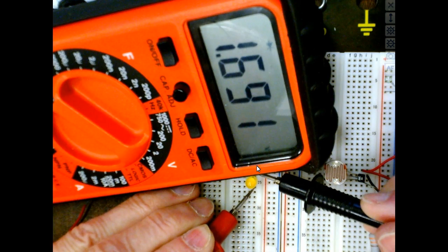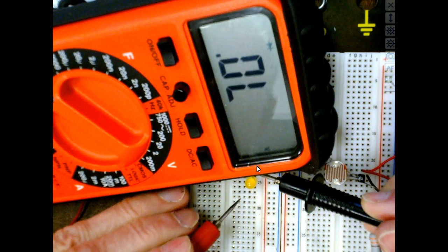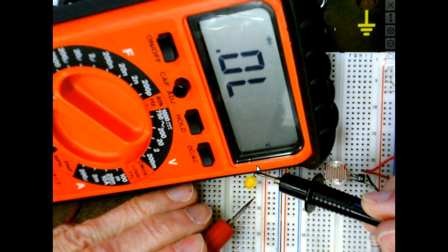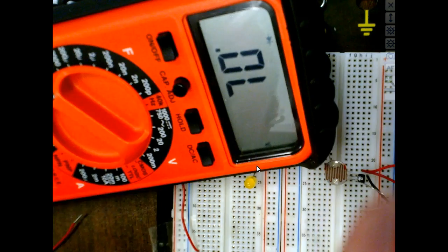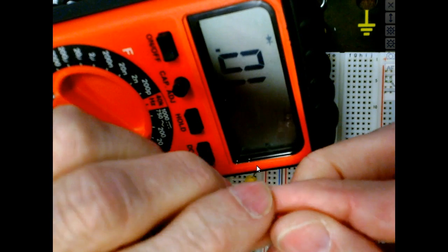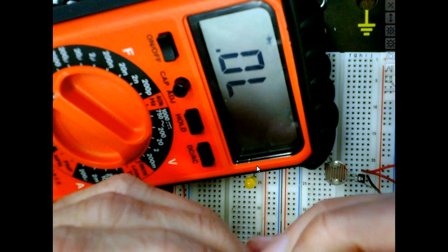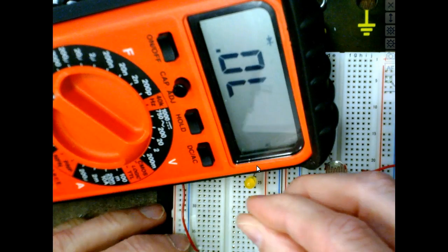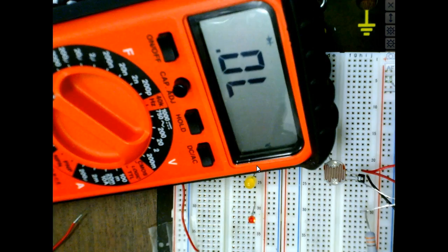Silicon is around 7/10. Gallium doped is different depending on the color. And let's see, nope, this LED doesn't come on. But I can take this tiny one right here. Here's the cathode, it's the short one. Double check it with the flat side. Then I'll put this in here. Odds are this meter will turn this one on. We'll see.